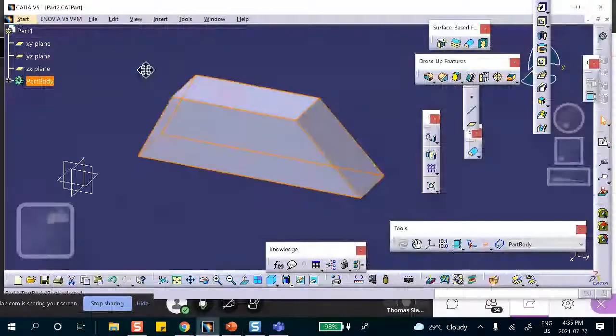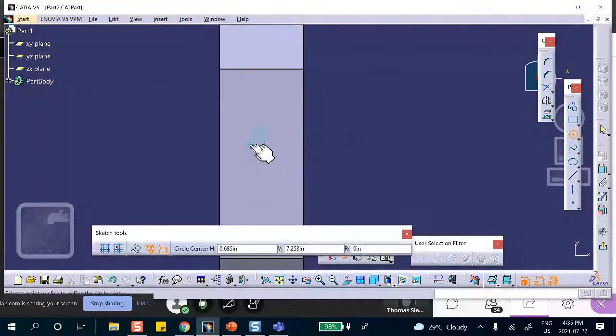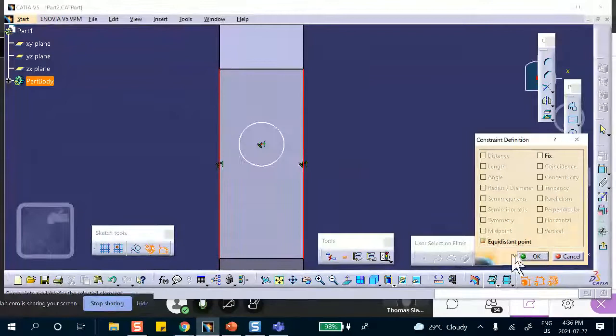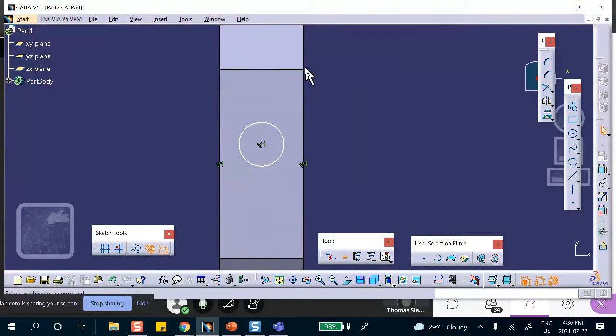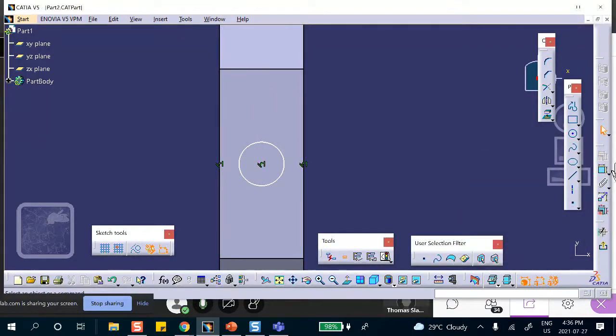Okay. Good. Now on that top face, I will sketch my good old circle. Center it nicely, because you're asked to do that. Left, control right, control the middle, center the middle. That's what I mean. Equidistant. And for the other one, you can do it like this if you want. This point, control that point. I'm doing it differently. Okay. Where is this guy? There, and then again equidistant. We'll do the same thing. You could have done top line, bottom line, etc. Exit,